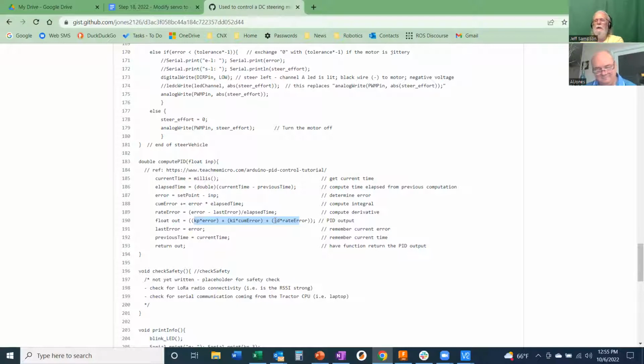And then you can say, okay, now set the position back to zero, and with everything set there, it should slowly attempt to work its way back to zero. And if you don't have enough proportional gain, it's not going to make it all the way to the target that you set. But that's a good way to start off and get it so it slowly moves back and forth. Then you start turning your proportional up, and it'll go all the way to your target. If you set it too high, it's going to go to the target, overshoot, go too far and bounce back and forth. So that's just something you can play with at that point.